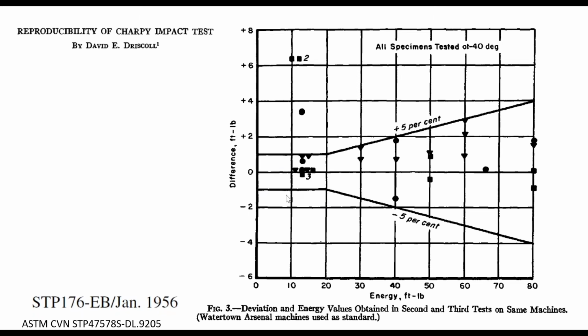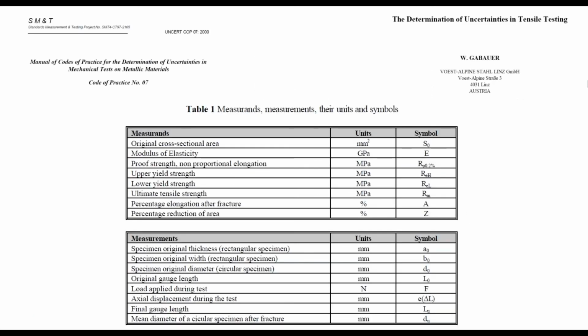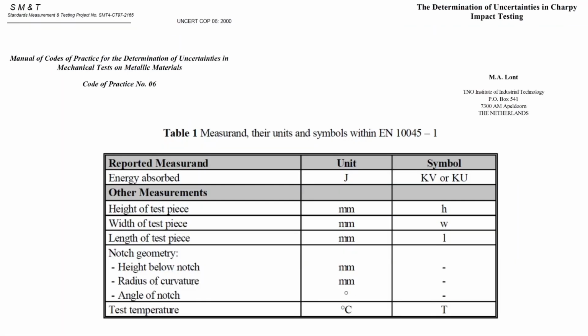most people that are technical believe that once you get under 20, and certainly once you get under 5, it's not clear how meaningful the Charpy value is because of friction in the machine and variations in the test. But once you get above 20, then it's a plus or minus 5%. So if you're within 5%, you are probably within the test uncertainty. This group for the Europeans also, for their code of practice, identified all the variations that give you the test uncertainty in Charpy V-notch.